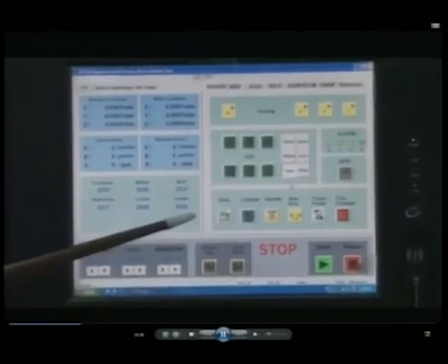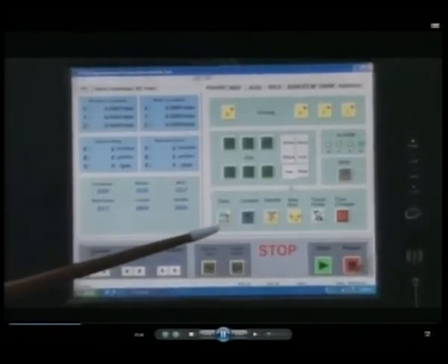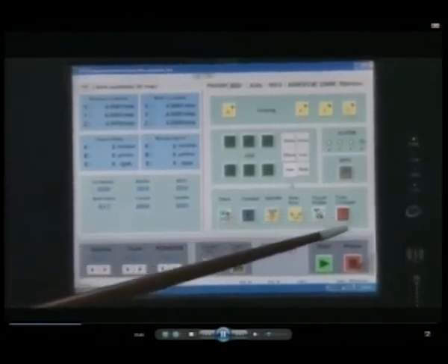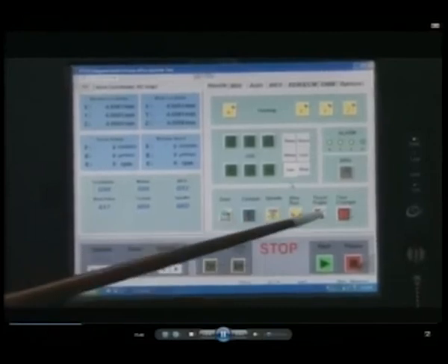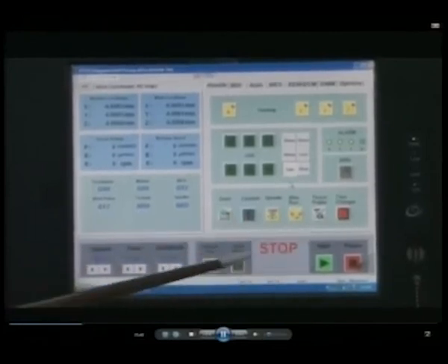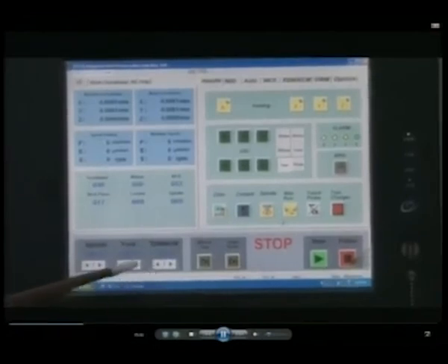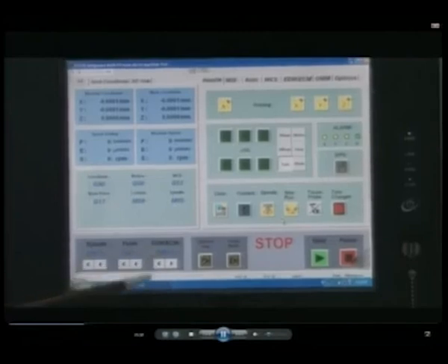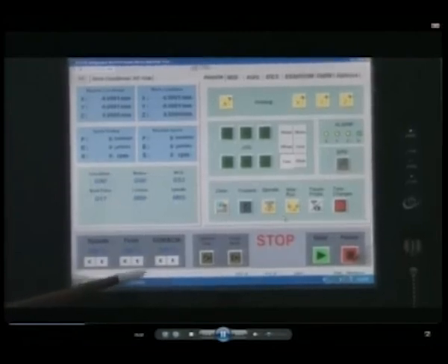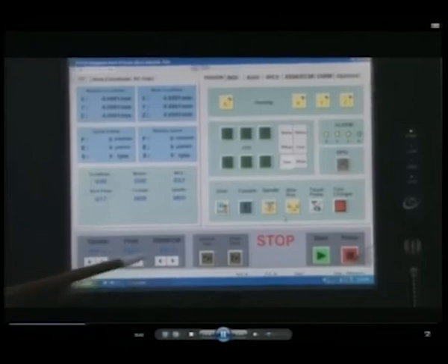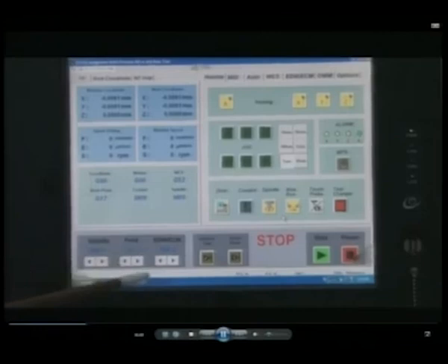The fourth command in the front panel has 6 options. All these are 6 different switches which perform 6 different operations. These 3 options are used to change the value of speed, feed, or EDM feed during operations. That is, during execution of a program, the speed, the feed, or the EDM feed can be varied by a certain percentage.